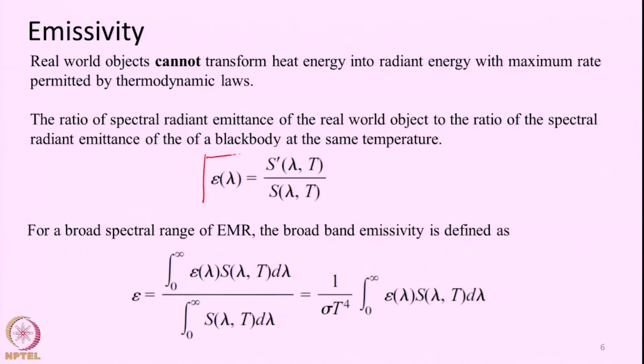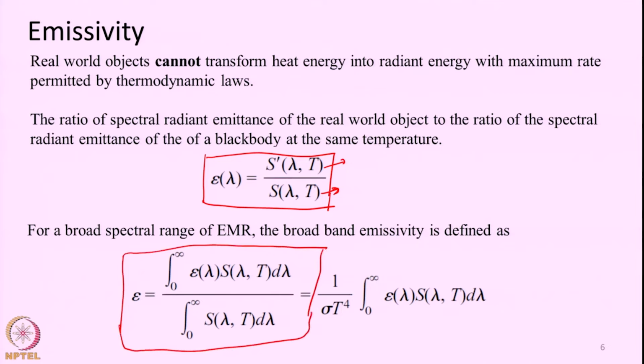So, this is the general equation that we normally use for calculating the emissivity: the actual radiation from an object over the radiation as governed by Planck's law. For a given spectral range, we can define a broadband emissivity like this, say between 10.4 to 11.2 micrometers. What will the emissivity mean? We can integrate these laws, or integrate the radiation, using these limits.